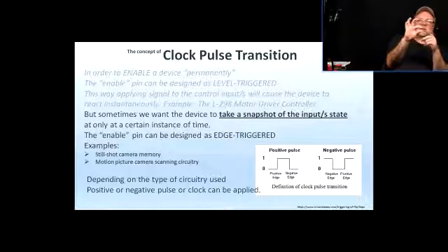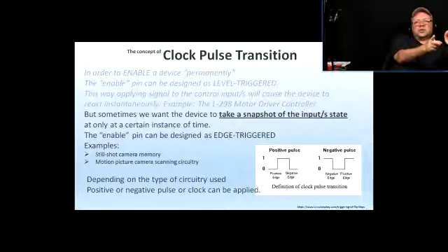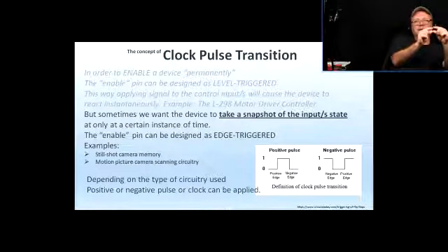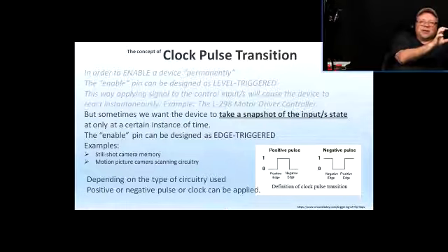And then when this motion sensor doesn't see the motion going anymore, it's going to close again. But that signal is sent to the receiving circuitry, and because it's a relay, it's a mechanical switch, so that signal will be debounced by whatever circuitry is there, and then sent to a device that latches that signal on. Because if it's a burglary alarm, then you want it to stay. We want this thing to stay.